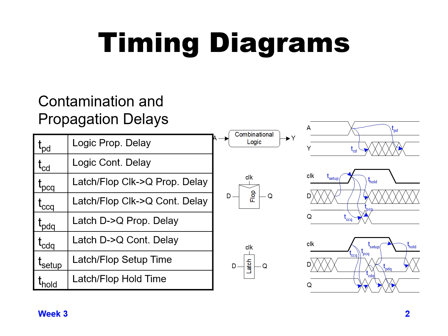So the T propagation delay, if you look at the top of the top two graphs there, where A has kind of the X there, it's saying you can either start with a 1 and go down to a 0, or start with a 0 and go up to a 1. Either way, the 50% switching point is where our time starts, and we want to know the latest amount of time. You can see the line and arrow for T propagation delay is the longest amount of time it takes for the output value Y to switch either from a 0 to a 1 or a 1 to a 0.